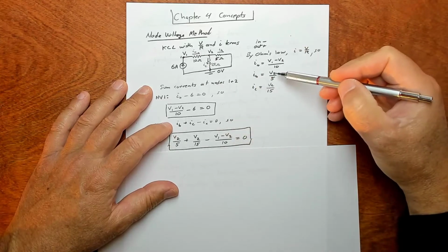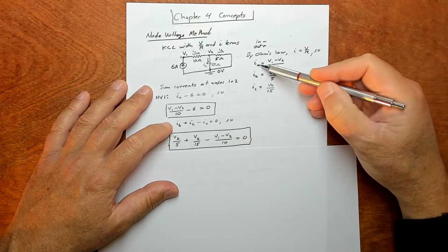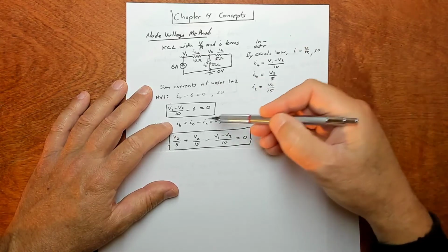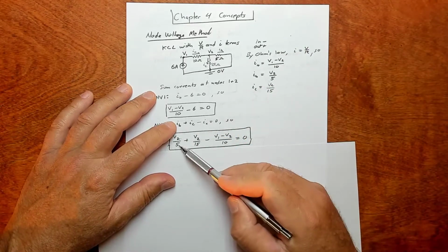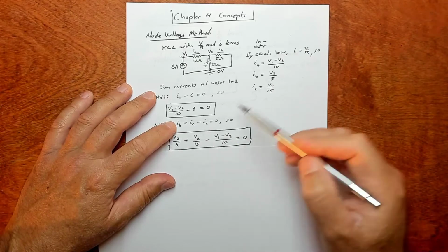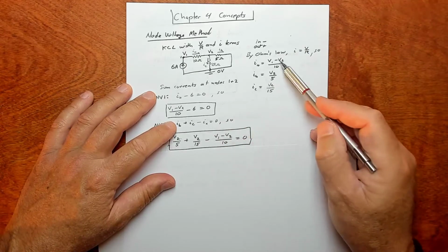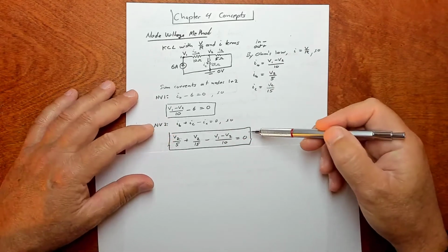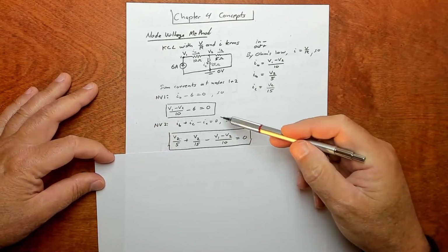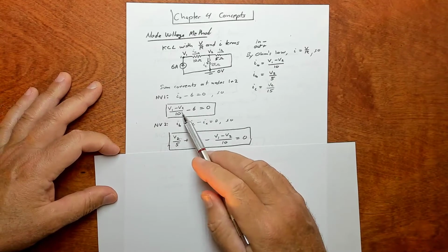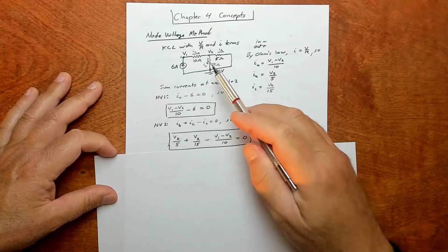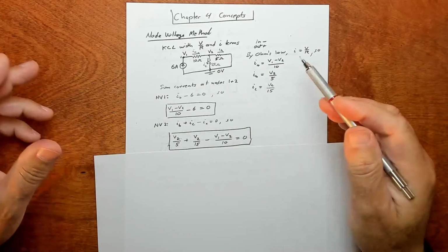Then once again, take your 3 equations for IA, IB, and IC and substitute them in here. And you get, for IB, V2 over 5, and for IC, V2 over 15, and for IA, you get this ugly thing. So this is the form that the equations take for the node voltage method. They're all expressed in terms of these voltages at different nodes. Okay, they look like that.